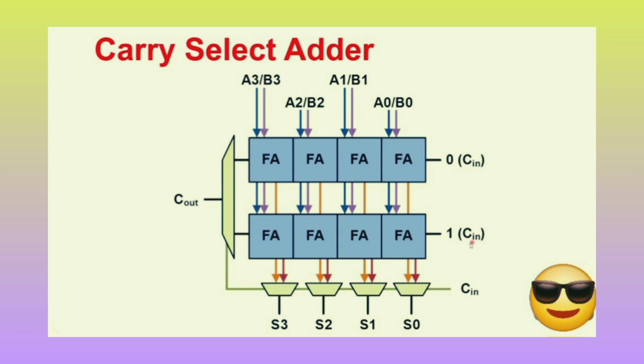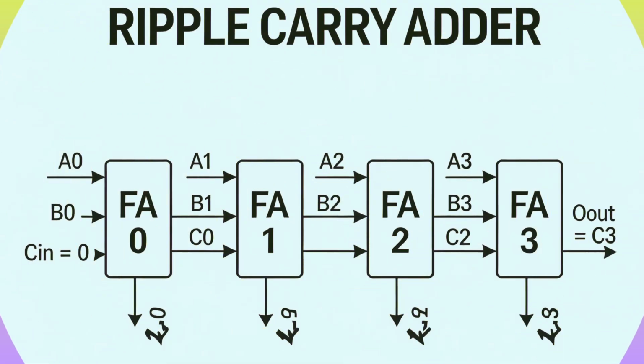In a well-designed system, the full adder computation time and the carry in arrival time are balanced so that the carry arrives approximately when or slightly before the full adder rows have finished, making the multiplexer delay the only additional cost beyond the parallel computation.